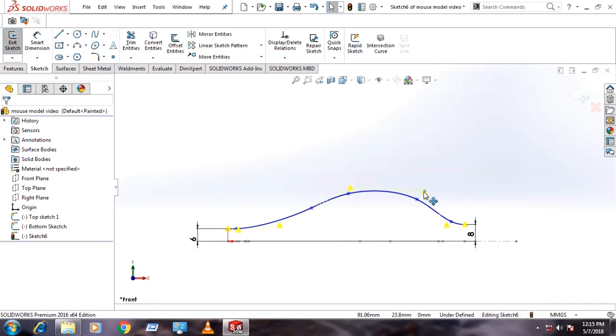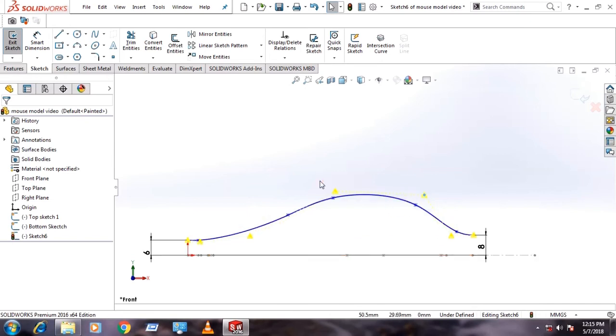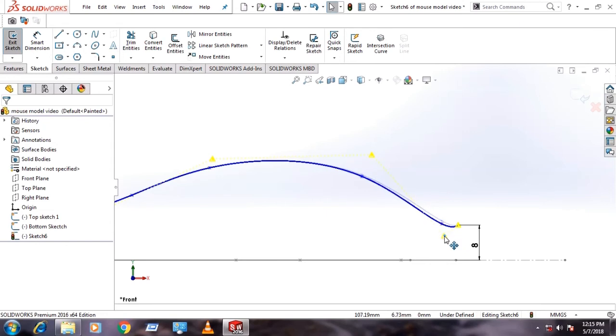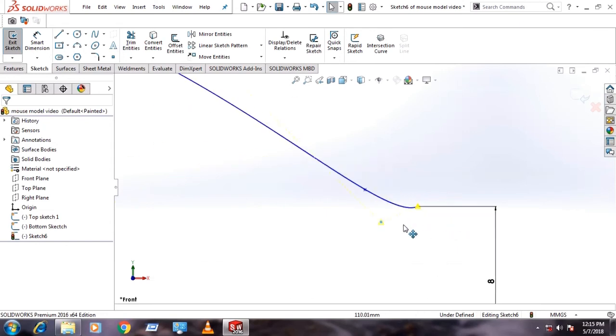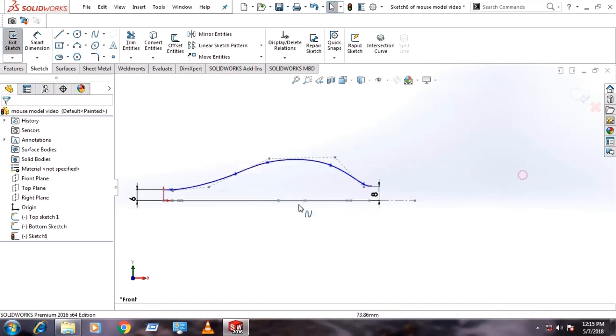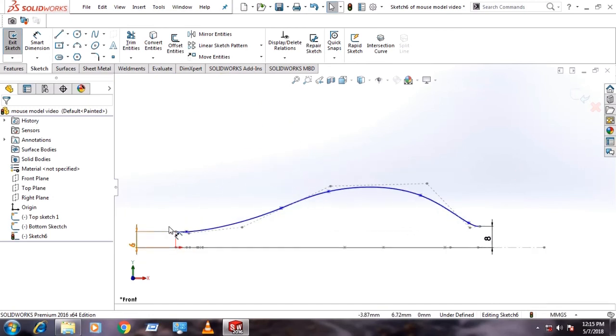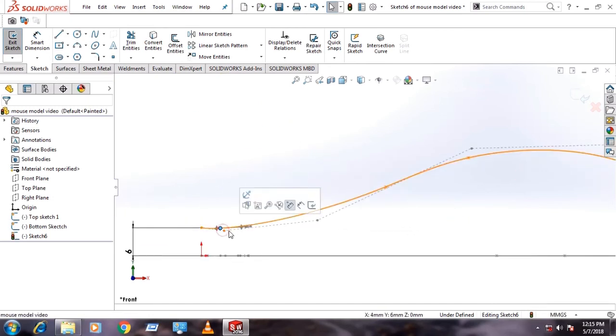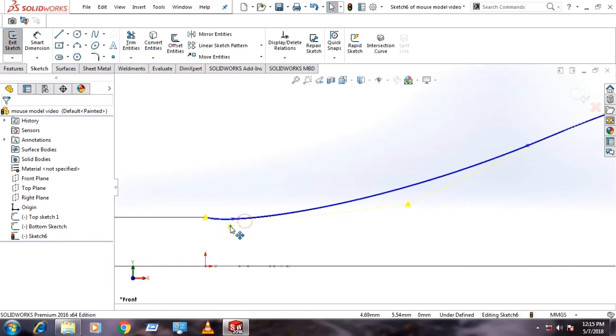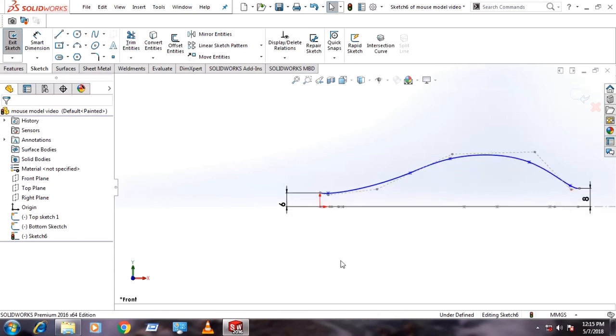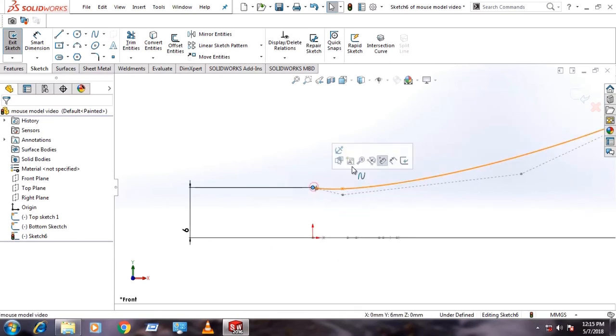Use the front view in the reference blueprint for getting this sketch correct. Adjust the control polygon handles. Use control polygon handles to make large adjustments in the spline and use spline handles for making very intricate and small adjustments.